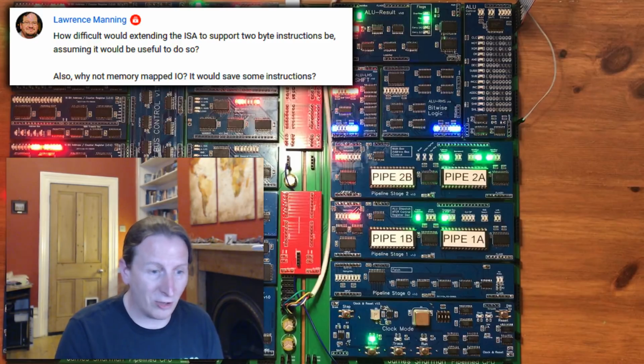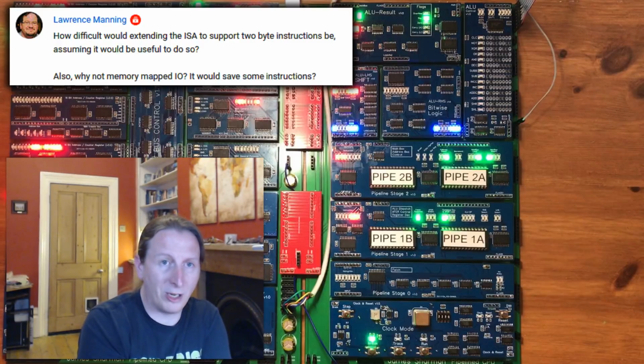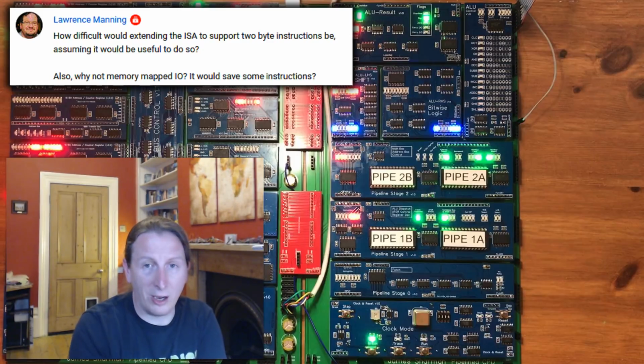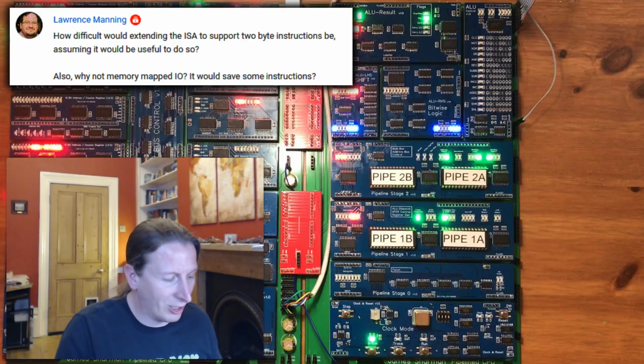But it would be nice to have the extra bits, because I could have more registers. The number of instruction permutations is really the cap on my register count here, and it would have been really useful to have maybe 8 registers. It would also be nice to have separate destination selection for the ALU operations, and the main thing that stops me from doing that is not an architectural restriction of the processor in any way, shape or form. It's just the number of instruction permutations I can fit into 8 bits.